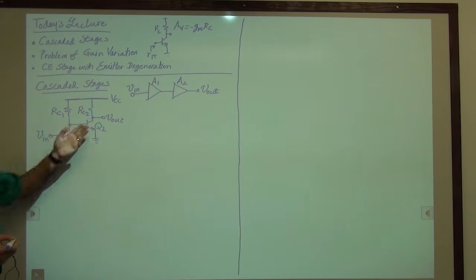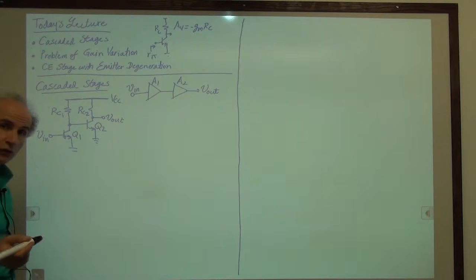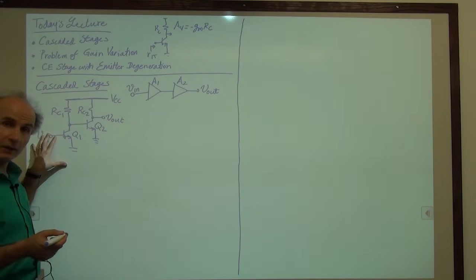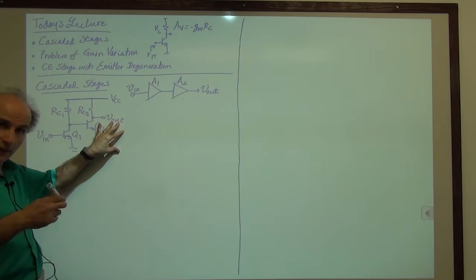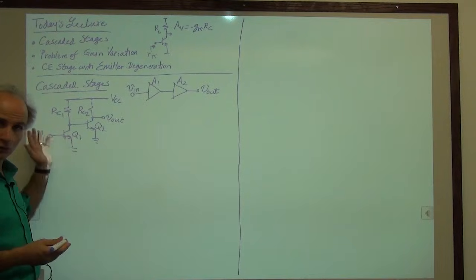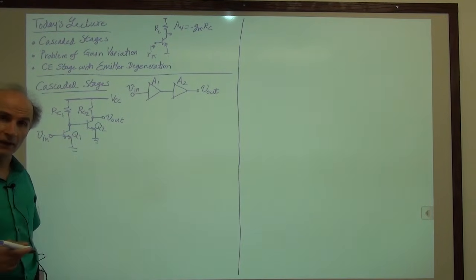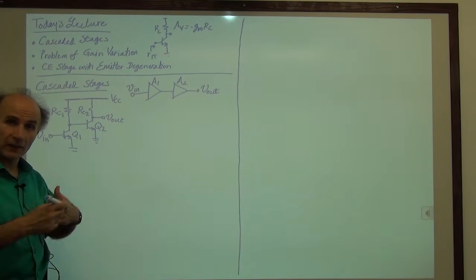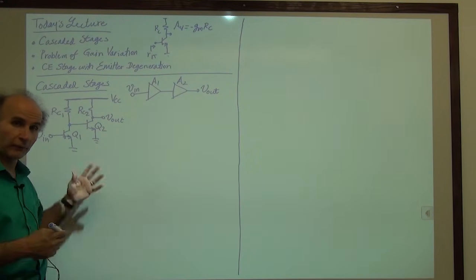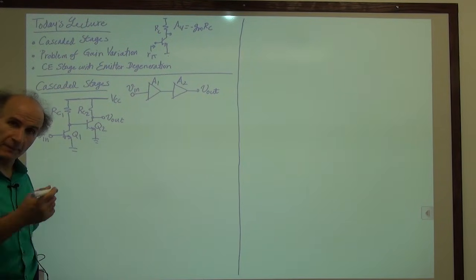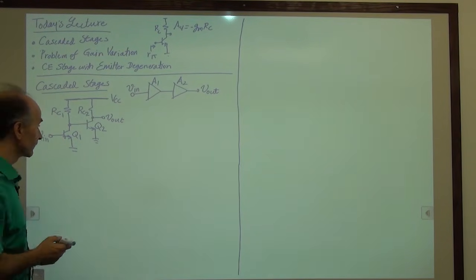All right, how do we go about calculating the voltage gain? Well, we could draw the small signal model of this entire circuit, replace each of these devices with its corresponding small signal model, and then just write equations. That's not that hard. But if you are lazy, can we take some shortcuts so that we don't have to do all of that? Maybe we can simplify things. So let's make some observations and see.